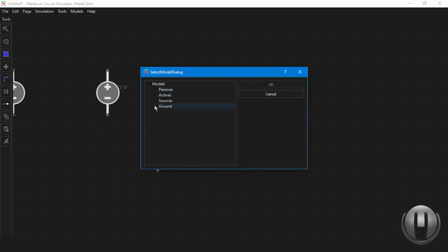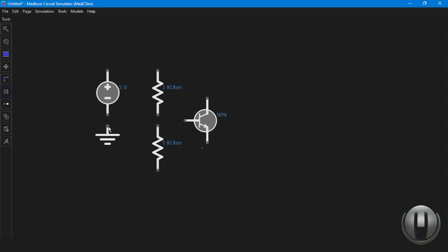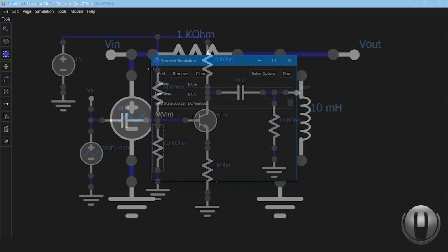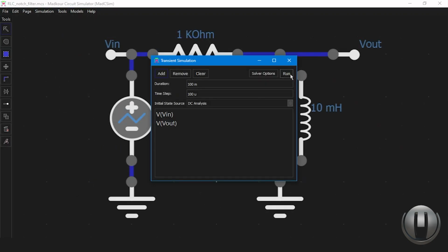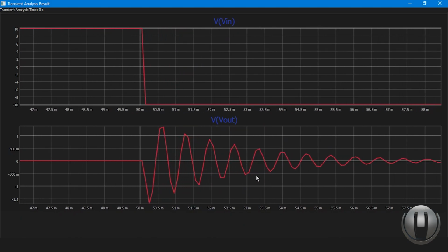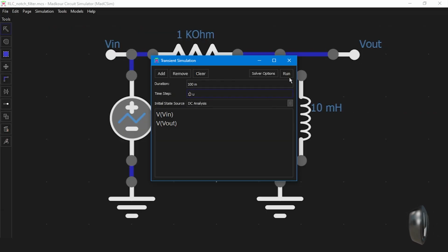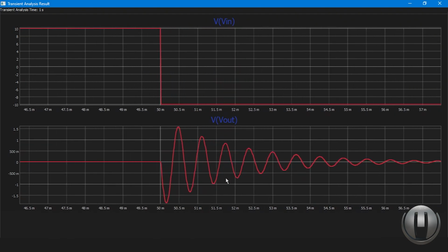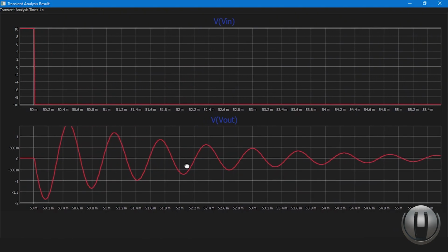Because the system of equations is exactly determined, it has a unique solution. But I won't get into the mathematics of solving linear systems in this video. All that was to solve the circuit at DC or a single time point. But if we want to see the behavior of the circuit with respect to time, we have to solve the circuit at each time step, making sure to choose an appropriate time step, small enough to capture the transient events, but not too small to increase the simulation time.